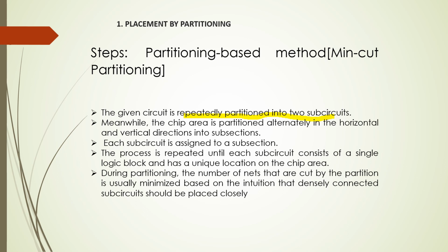The process is repeated until each subcircuit consists of a single logic block. So we keep on repeating the process of partitioning so that we get a unique location on the chip area. When partitioning, the number of nets that are cut by partitioning is usually minimized.